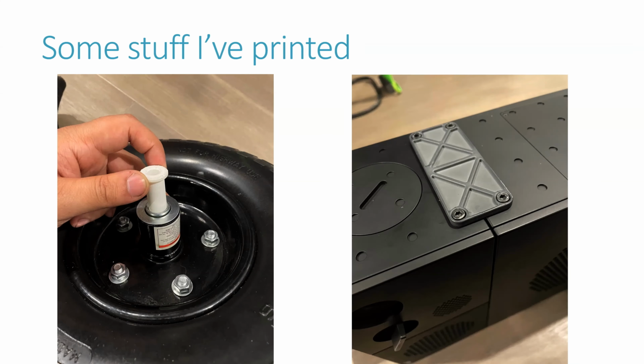Awesome. I can also address that question from Fong as well. But please feel free to jump in with your experiences. Fong, it's a great question about how to get metal out of a 3D printer. A couple different options. One is to use a metal 3D printer, which they exist. They tend to be quite a bit more expensive than the SLA offerings Formlabs has. Another option is electroplating, which is a process of painting a part with a conductive paint and then dropping it into a complicated acid bath with a block of metal, and the metal will move from the block to the conductive paint on the part, and you'll get a really beautiful thin layer of real metal on the part.